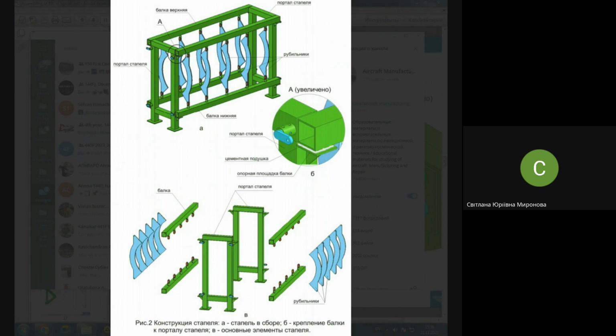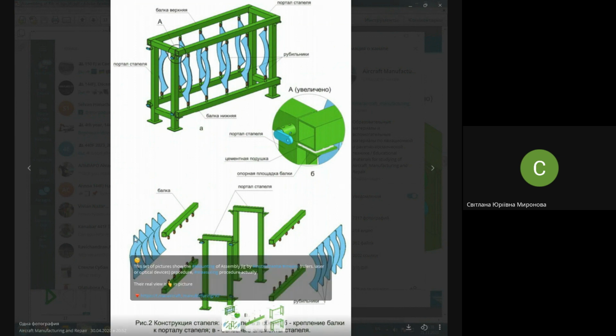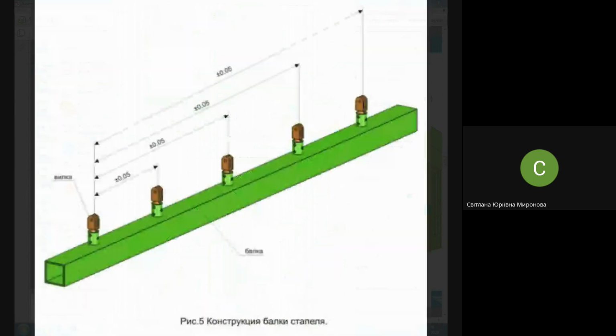They use again the instrumental approach. It means that they measure the position of jig elements. And what are they going to measure? They are going to measure the position of holes, so-called mounting holes, in locators with respect to the contour, and in jig beams with respect to each other in these fork-like connectors. Whether they are joined to cement or to break, it doesn't matter. Look, they are measuring position between a few locators actually, between these forks.